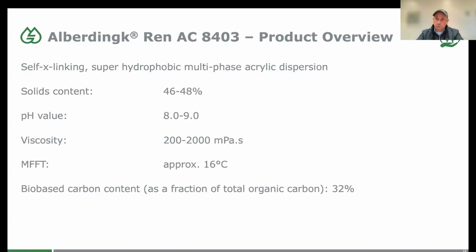We've got a solids level here of 47%. We've got a neutral pH. We've got a relatively low viscosity of 200 to 2000 millipascal seconds, and a low MFFT of 16 degrees centigrade, which is thanks to the fact that it's a multi-phase acrylic. And here, as the topping on the cake, you have 32% bio-based carbon content in the product, which can be analyzed with a C14 method.